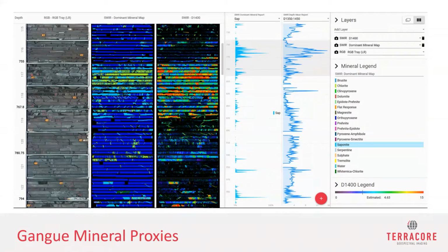So the Bushveld, typically what they like to mine is PGEs associated with coarse pentlandite and chalcopyrite. That's easy to recover by flotation. But when they hit these altered zones, they find that a lot of the PGEs start to move into arsenides, tellurides, become native metals, etc. And those don't recover necessarily quite as well through the flotation circuit.